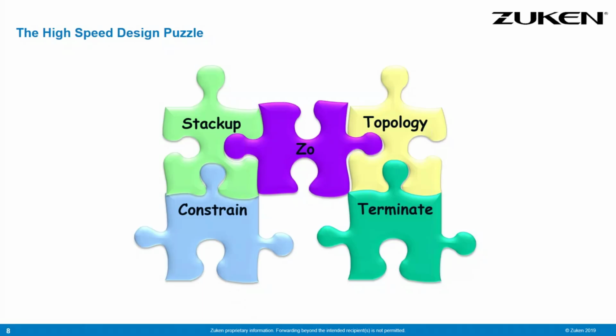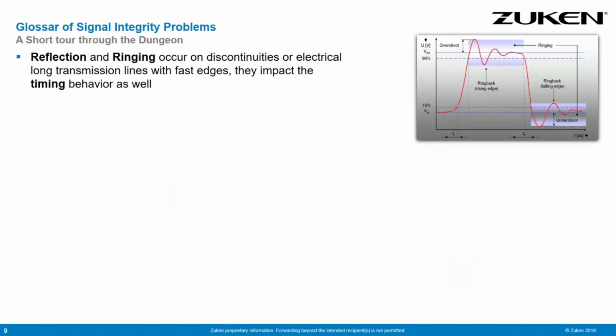So do constraining throughout the process. Start with the constraining as early as possible, probably even before you start the schematic of the board. And the whole thing should be supported, and that's pretty important. In an ideal situation, simulation should be a support process. Simulation should not just have the purpose of detecting errors, to do a kind of CSI PCB thing to find out what has caused my printed circuit board to die. Simulation should be helping all the other stages, simulation for signal integrity and for power integrity.